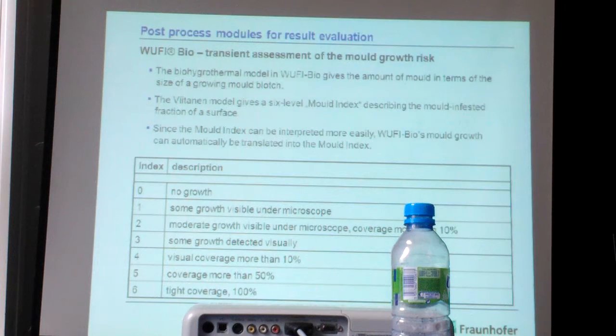The software has safety factors. Well, that risk goes from 1% to 100%, so it's not that useful at all. And it's contextual, isn't it? The sample you're taking, is it north facing? Are you taking a particular worst case? You choose the orientation in the software, and you can change it and check the risk. Exposure, height, air tightness and most things.